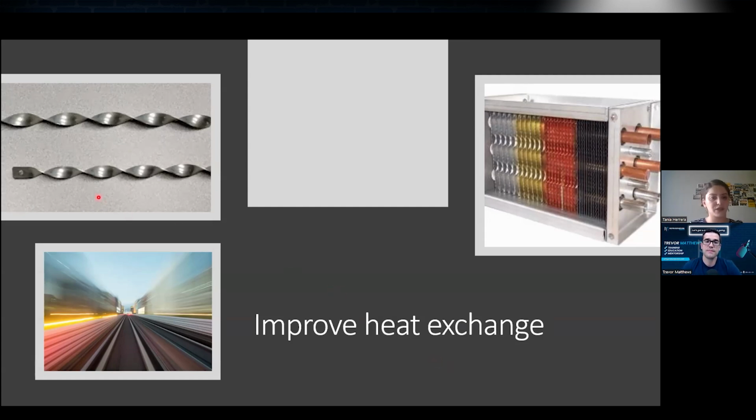We have these called turbulators that sometimes we use, for instance, for refrigerants that don't have a phase change, like the oil coolers, and also indirect expansion evaporators. We can't fill all our heat exchanger with these turbulators because this also increases the pressure drop of the refrigerant. So these would actually be in the tubes in certain locations.